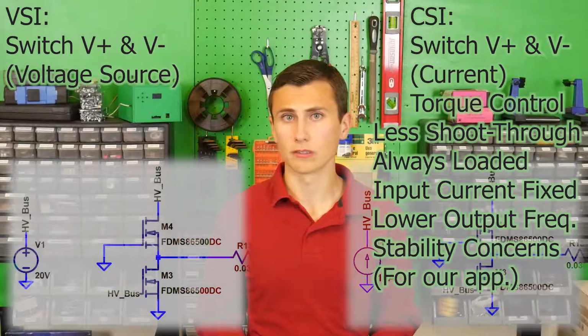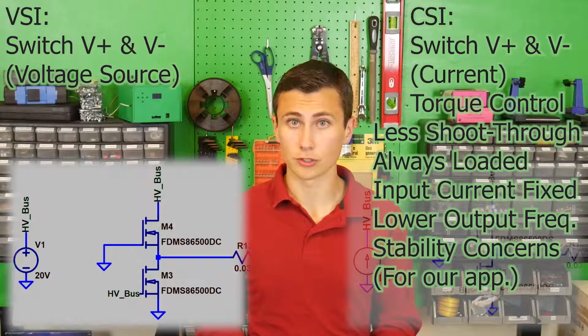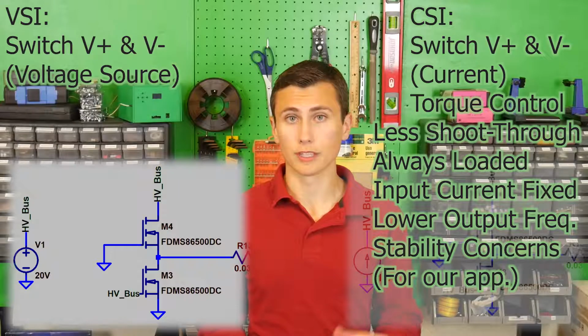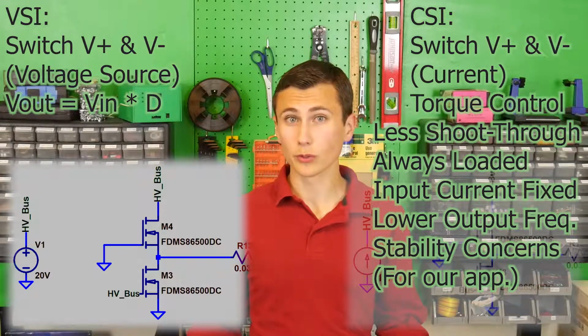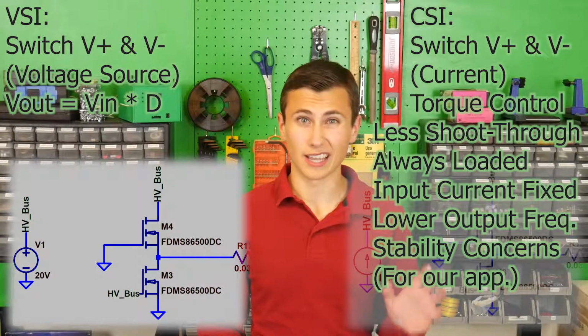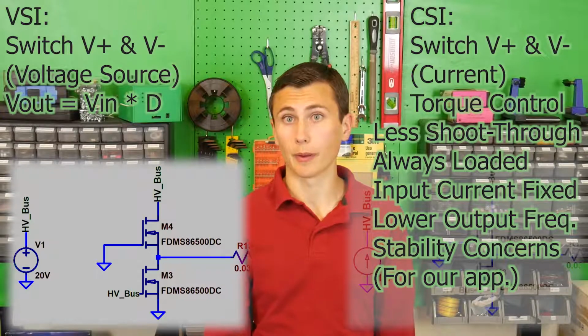What about the voltage source inverters? Voltage source inverters use a fixed DC voltage and pulse width modulation to regulate the output voltage. They ultimately create the output voltage by setting the output as a function of the input voltage times the duty cycle at any moment in time. How the voltage regulation actually occurs is a task for the control algorithm and isn't really a concern for us right now when we talk about the power output stage.